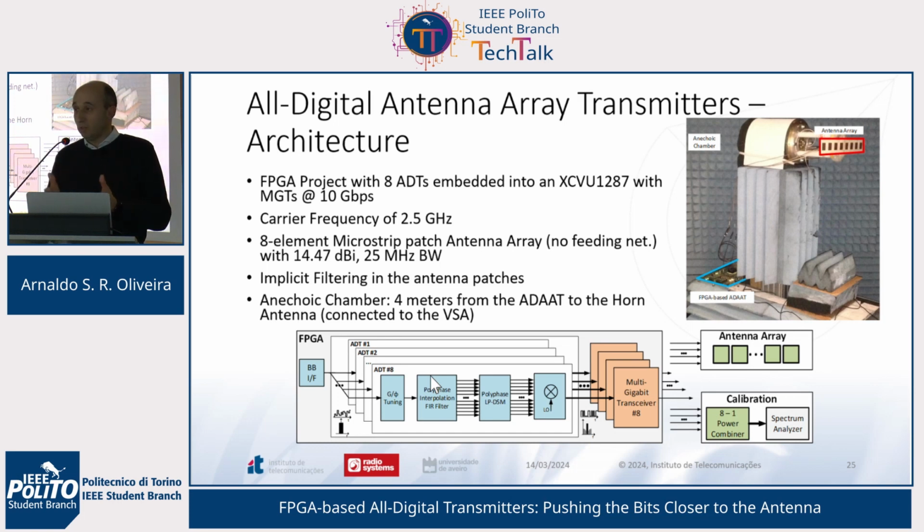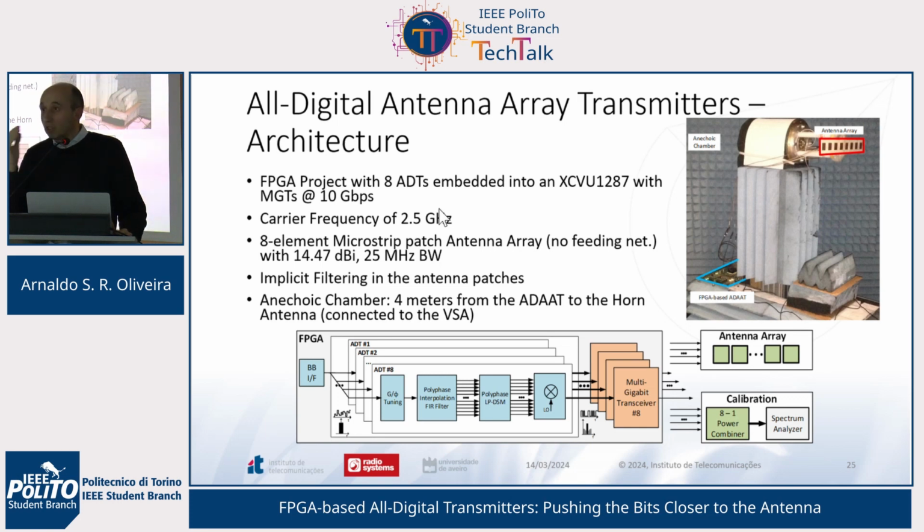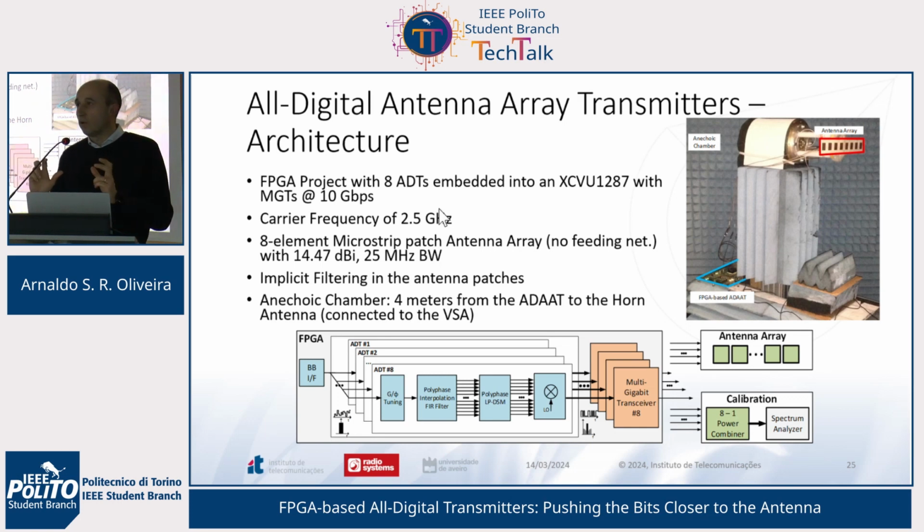In between we did not upgrade this approach to the latest transceivers, but it can be done, and it will allow us to push the frequencies we can achieve higher. The carrier frequency is 4 times lower, and this is a typical value for these transceivers. Typically we can reach carrier frequencies that are a quarter of the bit rate of the digital transceiver because of the way we perform the digital up conversion.